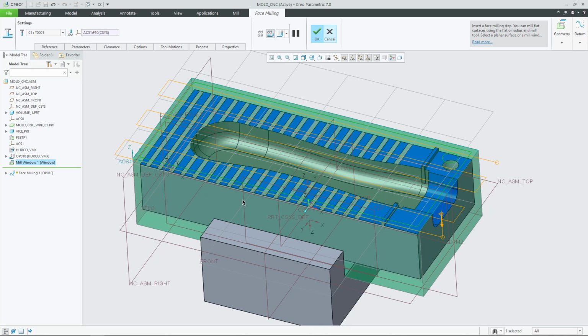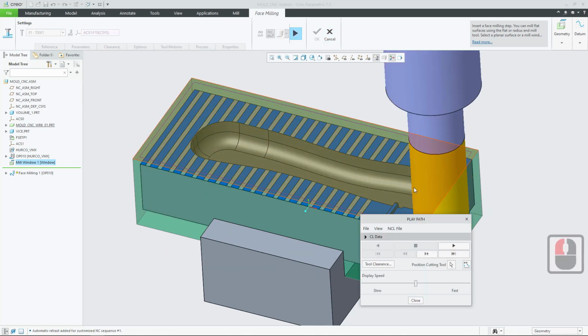And then at this point you may see on your system the tool path in orange marked out. So you can see this is where the tool begins, it travels down to the finished depth that it's going to cut out, and then it enters the part and cuts along here, and then it kind of hatches backwards and forwards across the part, and then it ends there. So if we want to see that sequence simulated, there are two main ways that we can do that. We can click up here, display the tool path in the graphics window.